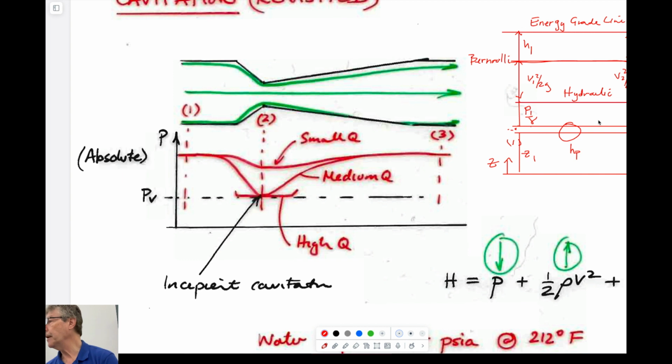That's not true in real pipes, because real pipes have frictional losses along the sides of them that use up the energy as heat and sound, perhaps. And therefore these terms come in here, that this is the pump head, not H1. This is the pump head that's added to it, and this is the head loss that's destroyed as you go down here.